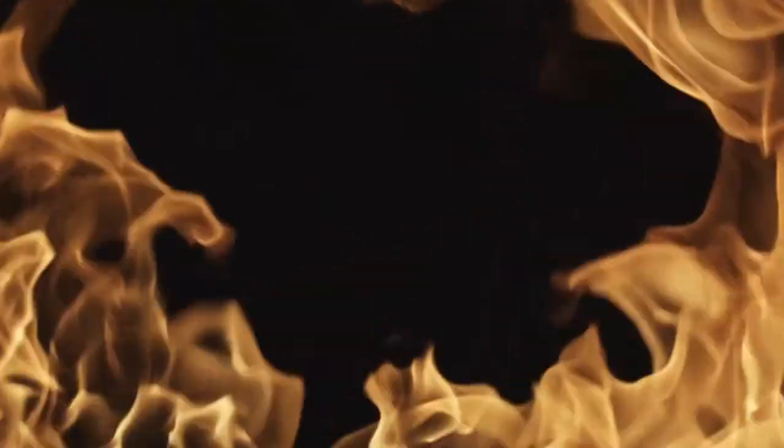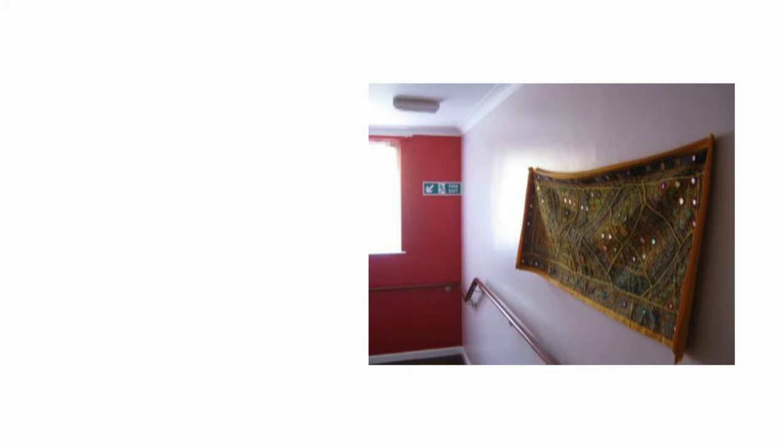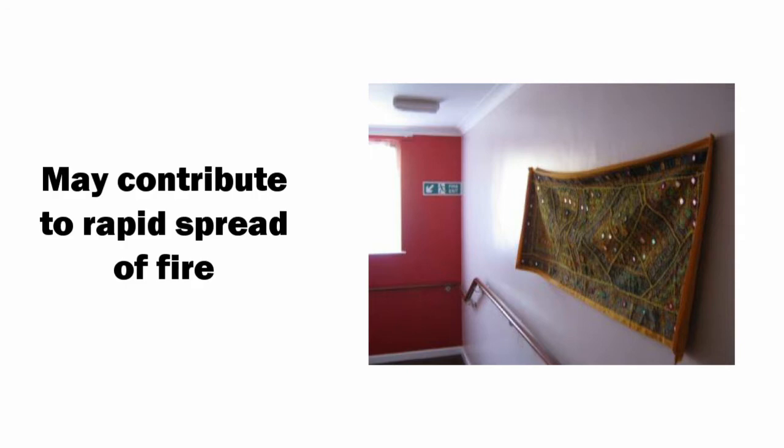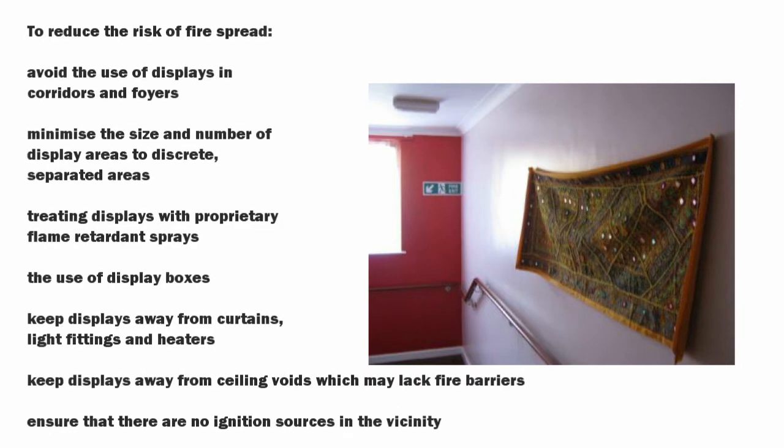To reduce the risk if there is a fire, consider how to control the spread of fire and smoke. Display materials and decorations. Displays are often located in corridors and entrance foyers, etc. They generally comprise materials such as paper, cardboard and plastic, which provide a means for the rapid spread of fire. The fire risk assessment should consider how these materials could contribute to the development of a fire in the area where they're located. To reduce the risk of fire spread, avoid the use of displays in corridors and foyers.